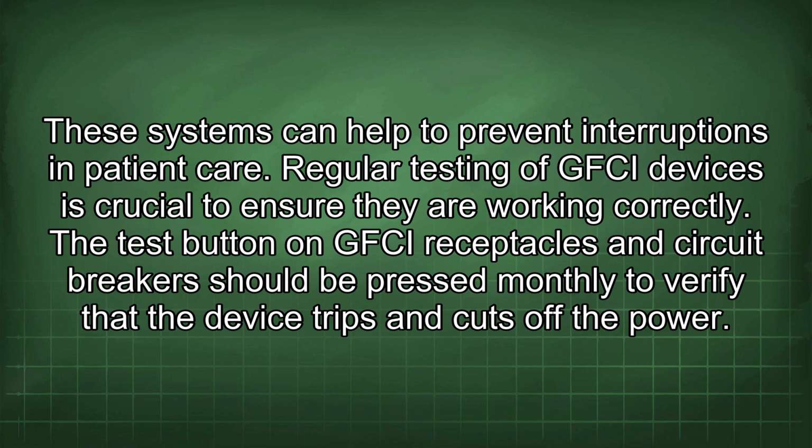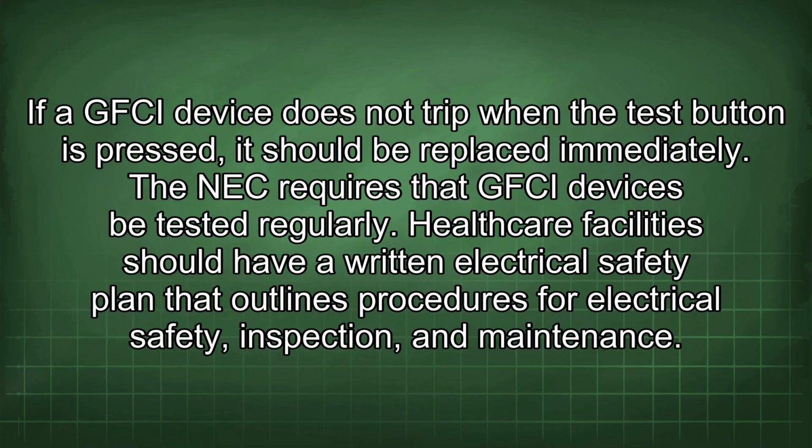Regular testing of GFCI devices is crucial to ensure they are working correctly. The test button on GFCI receptacles and circuit breakers should be pressed monthly to verify that the device trips and cuts off the power. If a GFCI device does not trip when the test button is pressed, it should be replaced immediately. The NEC requires that GFCI devices be tested regularly.